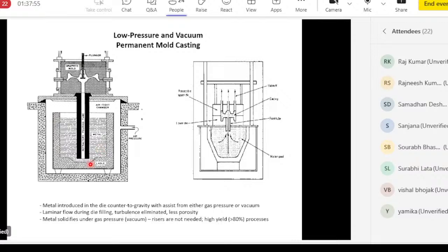I had many sensors, so I could track the movement of the metal. So once the desired height was reached, I would raise the tube above the metal and let it cool. What happened was something interesting. I was running this process and I was building up pressure, but my sensors in this tube were not registering the rise of the metal. This is a black box, so you cannot see what is happening inside. So we had to abort this. We opened this furnace or pressure chamber. What we saw was this.